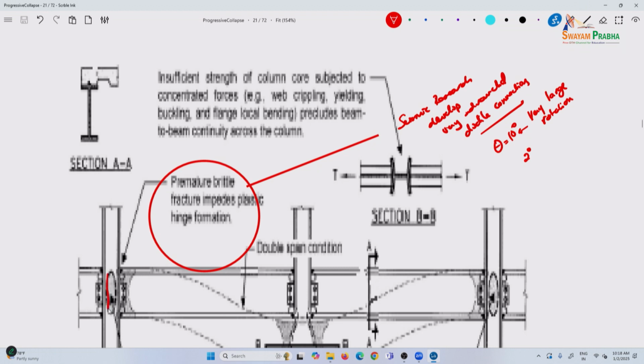In steel design, we know that a lot of the shear resistance is provided by what is known as the panel zone. I am not going to get into it. When you are designing a moment connection, you are going to be designing for these stiffeners, and you are also going to be designing for shear in this panel.